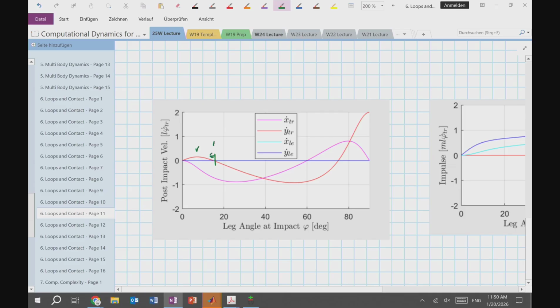And this happens to be 15 degrees. So for angles that are smaller than 50 degrees, my front foot hits the ground, the hind leg comes off. And this passive walker, this is what we saw in the demo, can continue to walk. Right? This is when we hit the ground with a fairly small inner leg angle, in the collision, our hind leg comes off. Human walking is more complex because you have knees and ankles and ankle push-off and wobbling masses. But in principle, this is how it works.